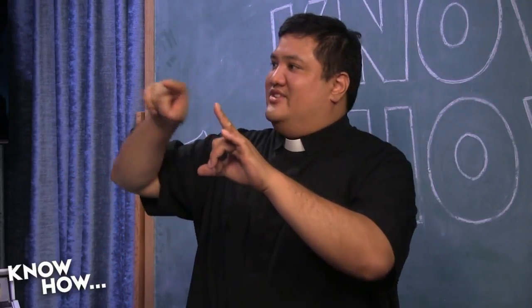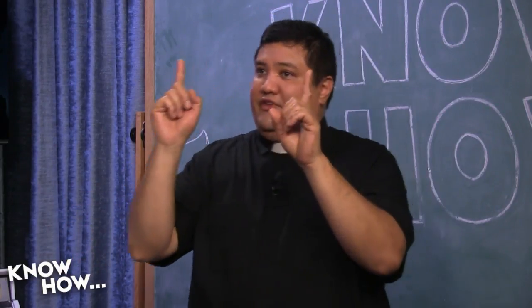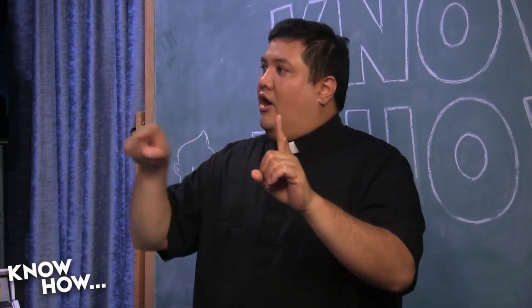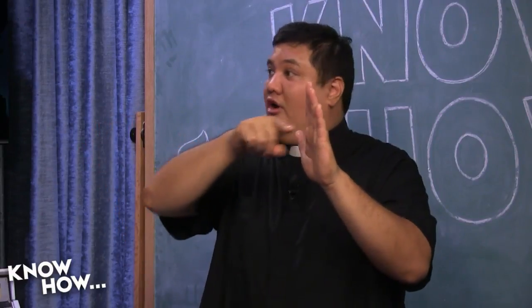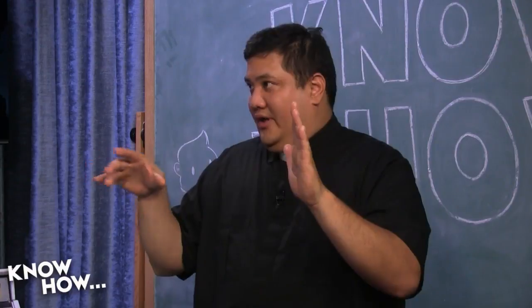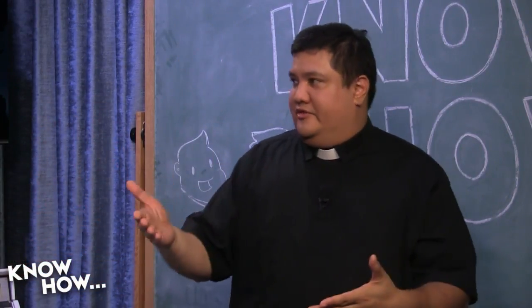Now you remember PWM deals with how the signal is pulsed. It's pulse width modulation, right, PWM. So for example, for every cycle, there's on and there's off. And the ratio of on to off determines what value you have. So if it's all off, it's 0. If it's just on for 1, you get 1, 2, 3, 4, 5, all the way up to 255, so 0 to 255.